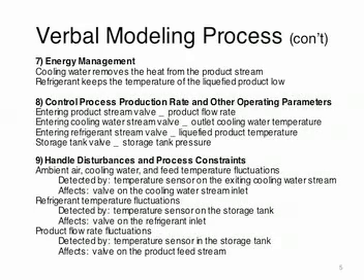The 4 valves from the system control 4 different parameters, including the flow rate of the product, the temperature of the outlet cooling water, the temperature of the liquefied product, and the pressure inside the vessel. These valves will react to different disturbances and will change the parameters in order to make the process go back within its restraints.